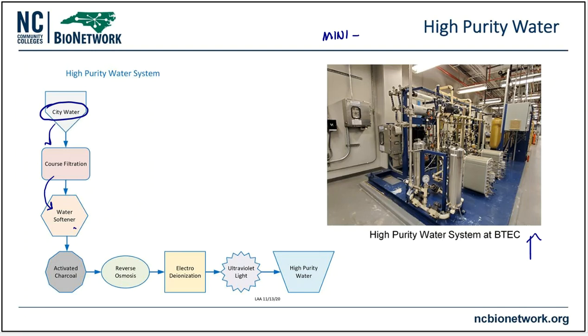Next up, after the water softener, activated charcoal is going to be our next, and charcoal is this way that we can remove organics. So once more, we talked about that as well. This is nothing new. We're just using our terms and our words now that we've learned in a little flow diagram and putting it all together. So this is removing all of the organics: organic solvents, fertilizers, pesticides, and so on. That's what charcoal is going to be doing.